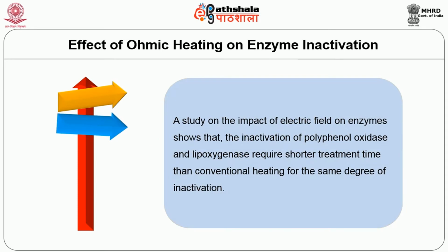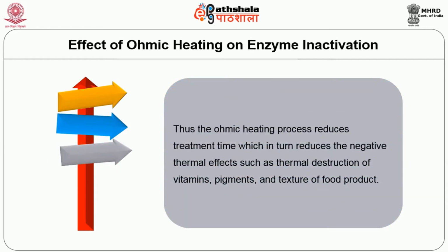A study on the impact of electric field on enzymes shows that the inactivation of polyphenol oxidase and lipoxygenase requires shorter treatment time than conventional heating for the same degree of inactivation. Thus, the ohmic heating process reduces treatment time, which in turn reduces the negative thermal effects such as thermal destruction of vitamins, pigments and texture of food product.